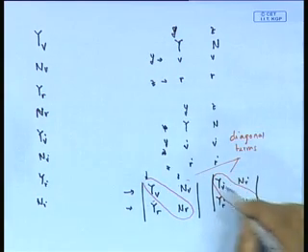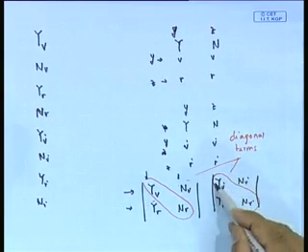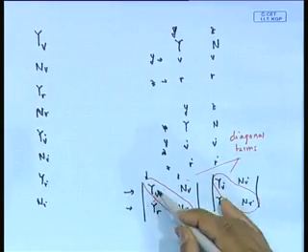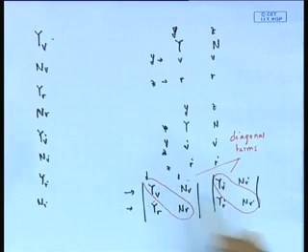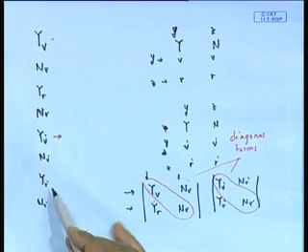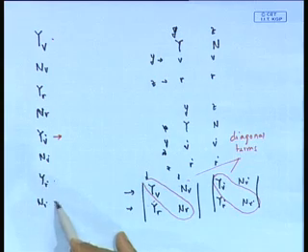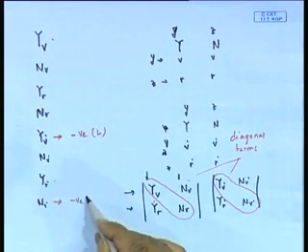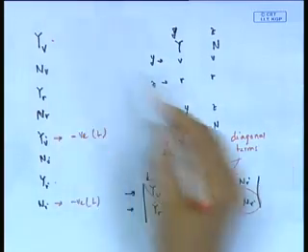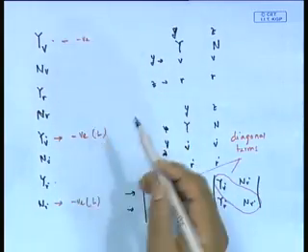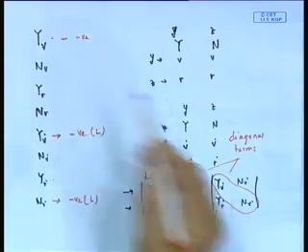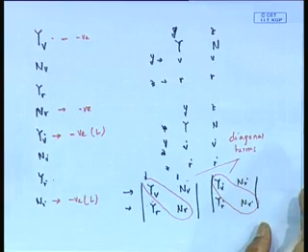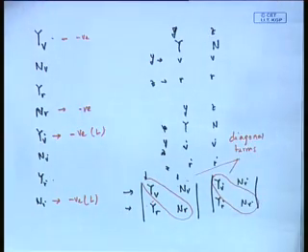Of which these two are added mass terms. This is actually sway added mass with a minus sign, minus of sway added mass, minus of yaw added moment of inertia. Why am I saying that? Remember, if I look at these two diagonal terms, yv dot, nr dot, large negative. Even these two are negative and fairly large. Okay, that is what we have found out in all these parts that we have gone through.